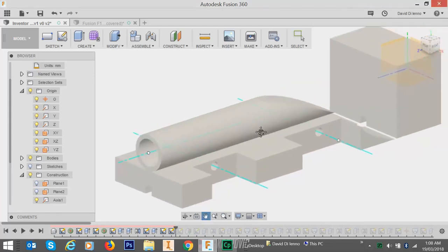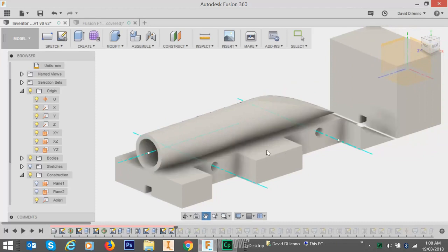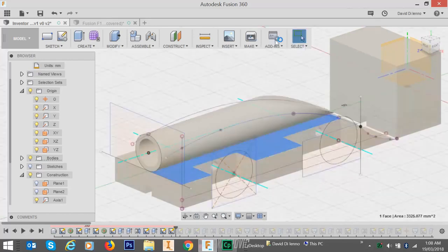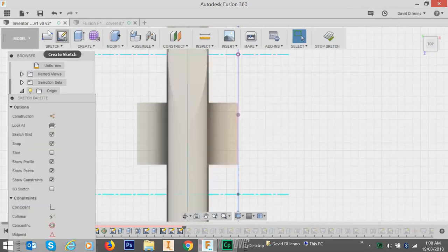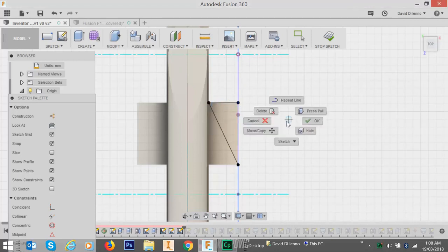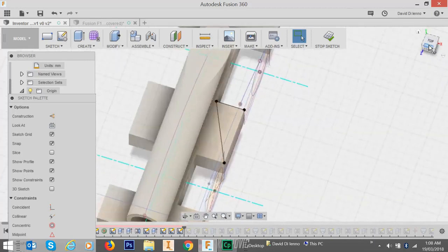We want to firstly streamline this side pod over here. So I'm going to select that area there and create a sketch on it, and I'll use a line tool to do that. So here's the line, and select point there, drag across and create a bounded shape, which I'll click OK to, and that bounded shape can now become a cutting plane for use